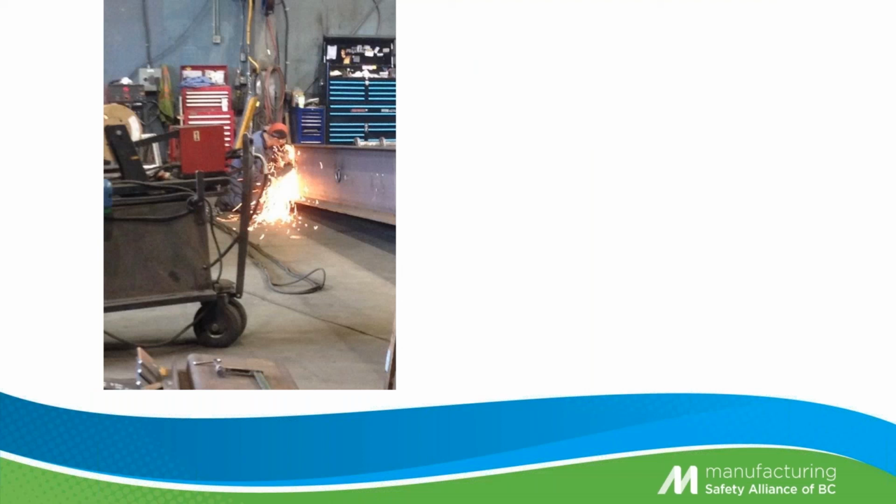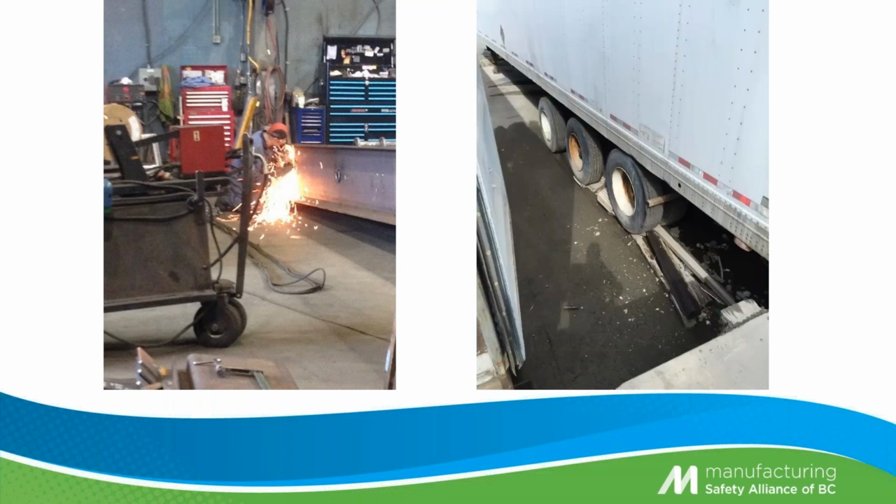Here we have someone grinding away. They probably should have a face shield. You can see that they're wearing eye protection, but with that amount of sparks going, you'd want a face shield as well. The next one is a trailer. You can easily buy or manufacture these. So if your loading docks don't line up, what this did is present a major tripping hazard because the trailer didn't match up to the dock.